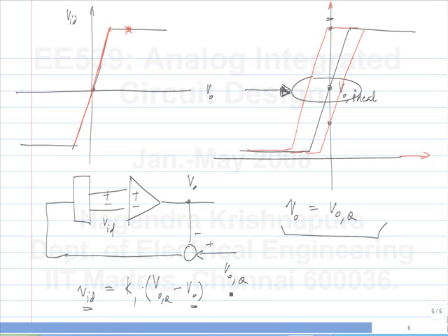But this should happen at DC, right? So when we were making different signal processing blocks with the op-amp, we didn't really say anything about a particular frequency. Whatever transfer function we want, we can realize by appropriately adjusting the feedback circuit. But this is something else entirely. This is because the op-amp is not biased correctly without DC negative feedback. Whatever circuit you make must provide DC negative feedback around every op-amp.